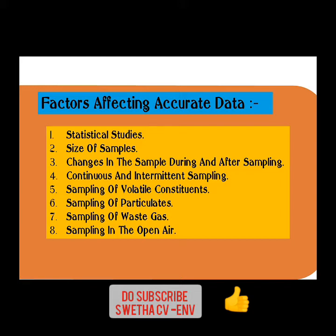The other thing is the surface should be very near, so that collecting the particulates will be easier. In case of sampling of waste gases, here also they find it difficult to analyze. Why? Because here the temperatures will be very high, due to which the gases will get disturbed, their speed may vary, and thereby the analysis may get disturbed. So what they do is place sample collection units at certain points, collect a sample from each unit, and at last do an average analysis to get an accurate value.